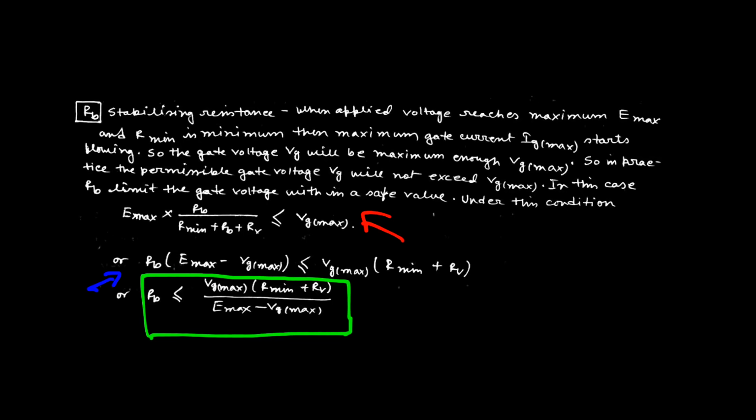So this is all about the resistive firing circuit. We can conclude that we are using particular resistance values for Rmin, RV and RB, through which we can apply the permissible amount of gate current as well as the permissible gate voltage within a particular region, so that the switch can be operated without any disturbance, and no accident will occur when using this kind of proper resistive circuit. So this is all about the resistive circuit. So thank you.